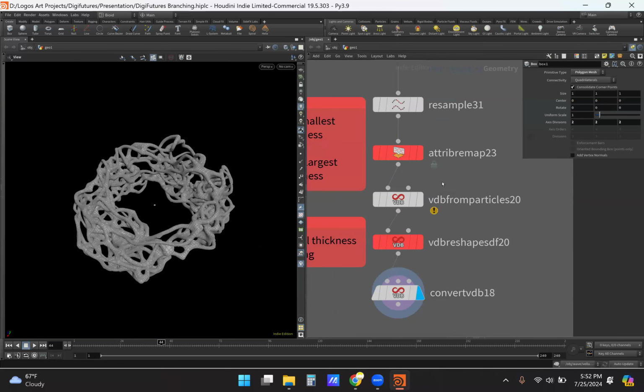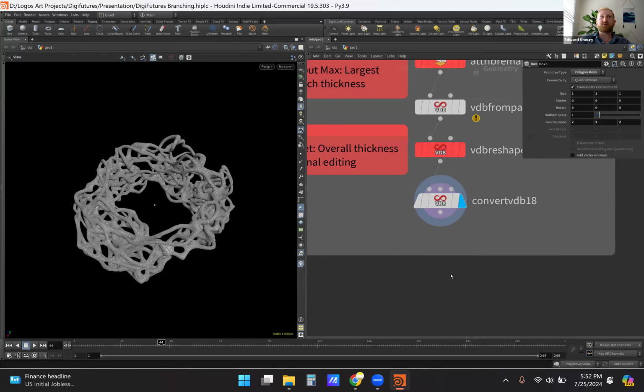Yeah, so someone asked about exporting as STL. I think I recommend first exporting as OBJ, bringing it into Rhino. Through the past for me personally, I feel like bringing it into Rhino helps, you can clean the model and I feel like Rhino makes better STLs. But that's just through my own experience. Everyone has their own kind of workflow. I often just bring these into Rhino as OBJs.